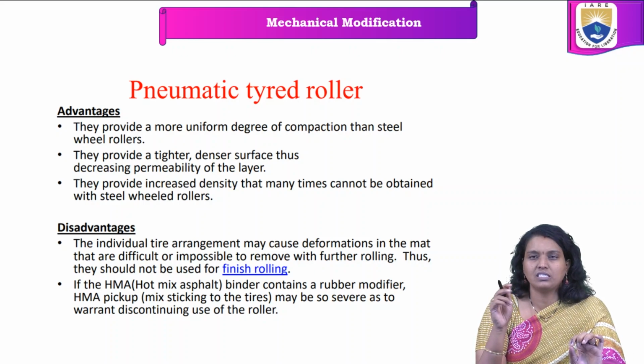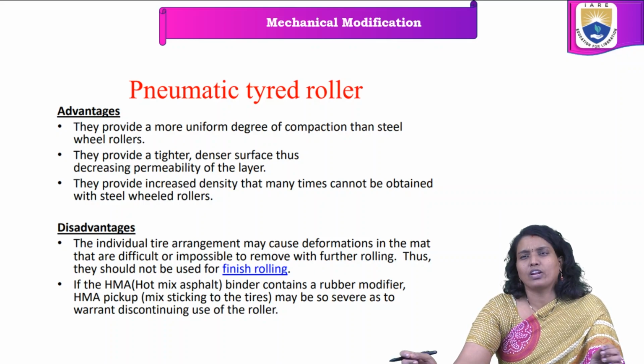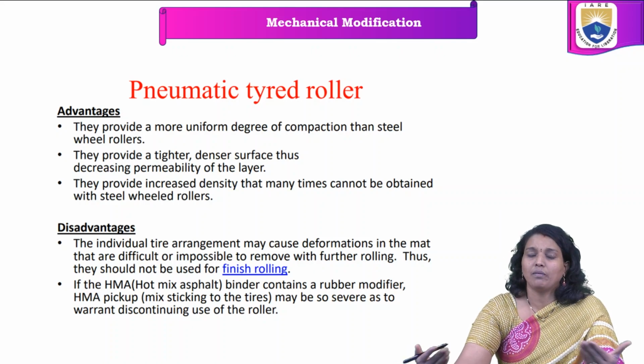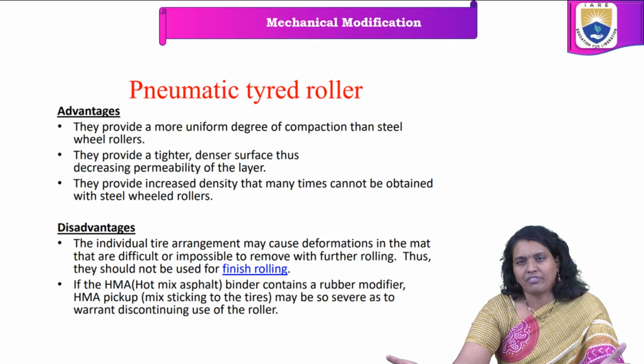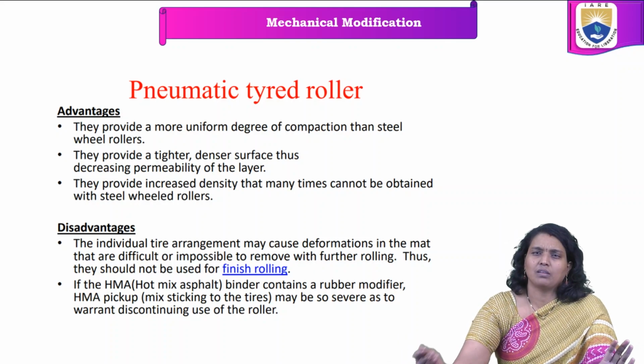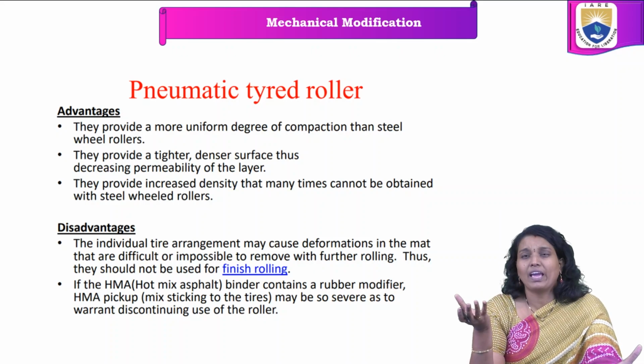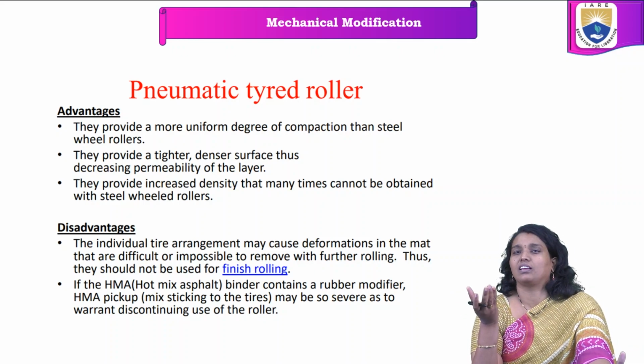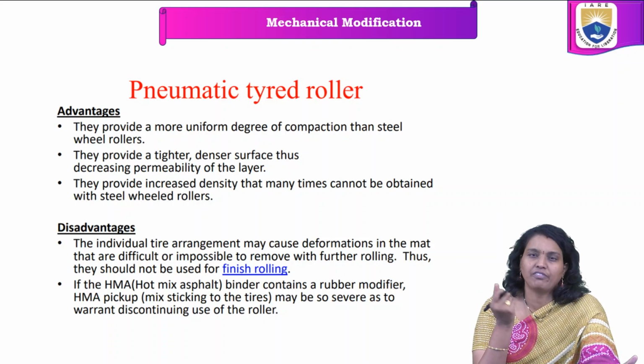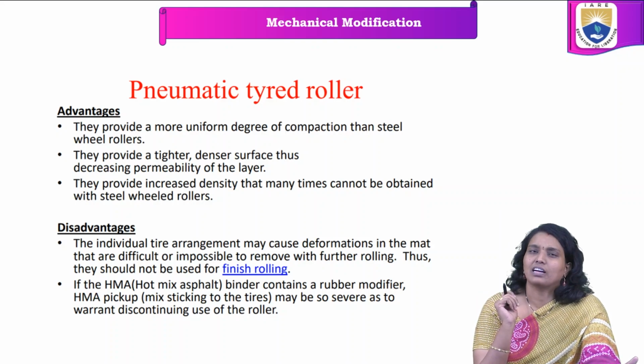So this kind of roller should not be used for finishing rolling. Coming to binder contents, it depends upon the mix. The binder has different kinds of properties, and some stickiness may happen because of the combination of aggregates and different materials used for the construction work.